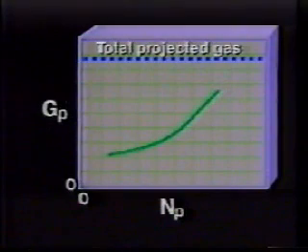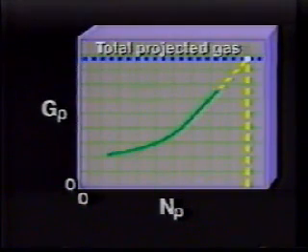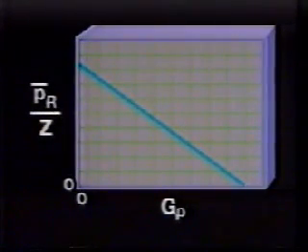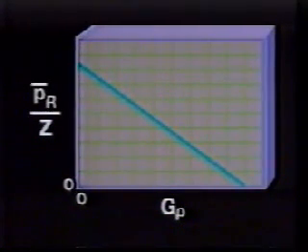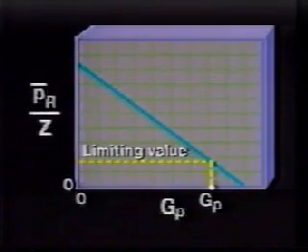If the total expected gas production has been calculated with a degree of accuracy and serves as our cutoff point, we would plot the cumulative gas production versus the cumulative oil production in order to find the total oil to be produced. Finally, we should add that for a gas well, the minimum producing rate is determined by the back pressure imposed on the well, with or without compression. When the value of this limiting back pressure is converted to a value of average reservoir pressure divided by Z and plotted on the pressure versus cumulative production curve, the quantity of ultimate producible gas reserves is obtained.